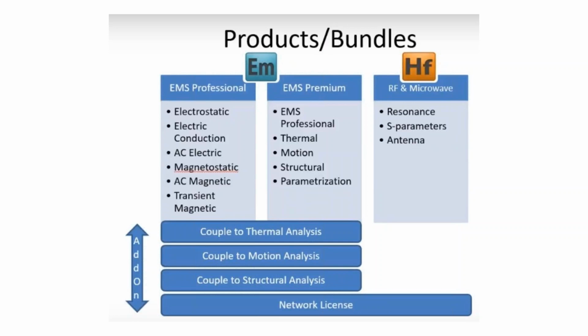Now there is one question about the fill factor for the coil. Definitely the fill factor of the coil is automatically computed, and if it exceeds the maximum value, which theoretically is 1, but in reality is much less, EMS is going to warn you about it and might even prevent you from running the simulation.